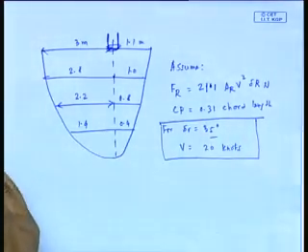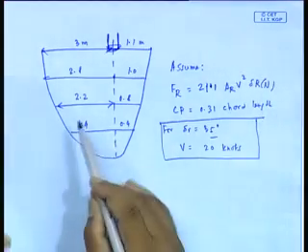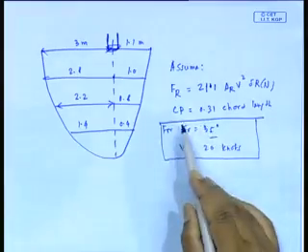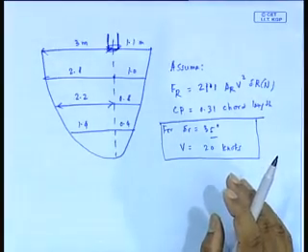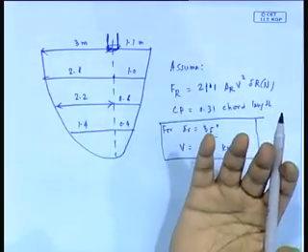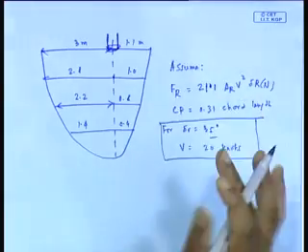It did not say, but I said that in such a case you have to choose one of the formulas. The formula we use here is 21.1 AR V square dr in Newton as the rudder force. This was the latter of the 3 simpler formulas I gave, but simpler than the CL CD form, and Cp is also a simple formula. 0.31 is used because we have seen that it is 0.31 if there is obstruction before, as it is a single screw propeller ship with one propeller. Now there is some obstruction in front.